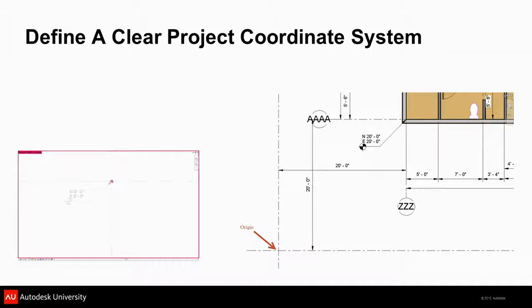One of the things I found helpful in that whole LOD piece is getting people that have a lot of experience in design or construction, and I'm talking a couple of decades, who can hone in and say, this type of building reminds me of one I did way back when. This is where we had all the coordination problems. It was in these areas. It was above the operating rooms. It was coming out of this congested mechanical area. It was the subgrade coming in through this part of the building. Then hone in and do higher levels of development and modeling in those areas, and coordinate those spaces out early and try to find the biggest problems.